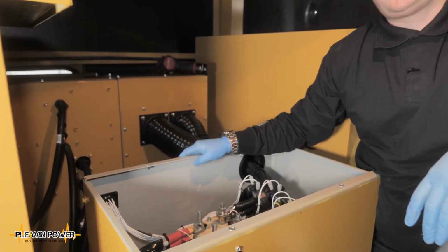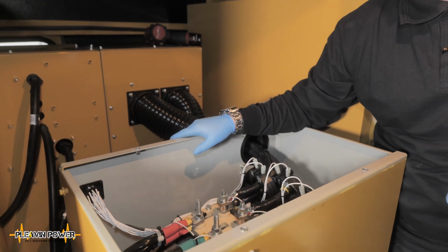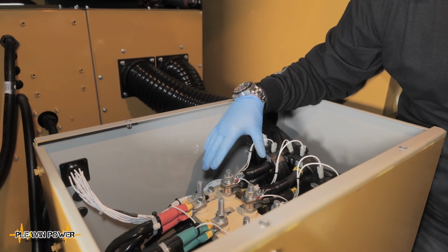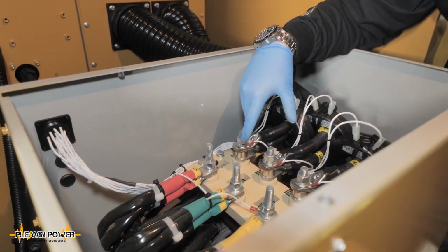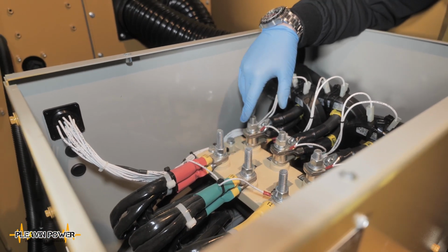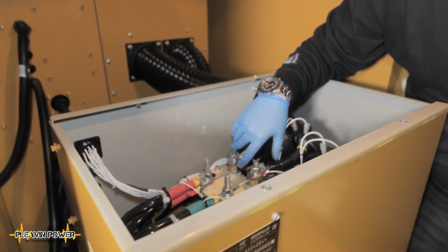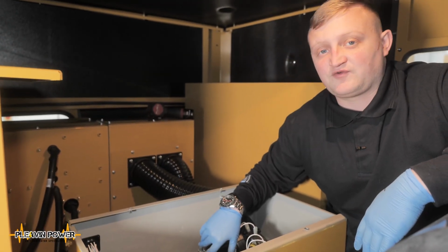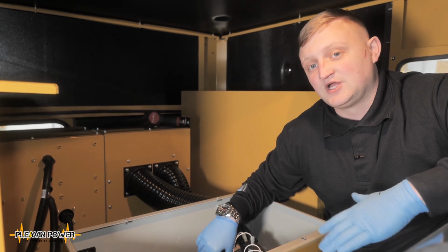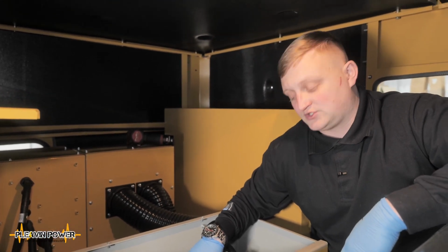Okay guys, let's talk about AC alternator maintenance, what's involved and what specifically this piece of machinery does. This is where the electrical production takes place while the engine is running. The engine needs to run at a speed of 1500 RPM to achieve 50 Hz, which is the frequency the UK or National Grid operates at. This varies depending on where you are in the world, such as in America where the frequency is 60 Hz and the engine is required to run at 1800 RPM.